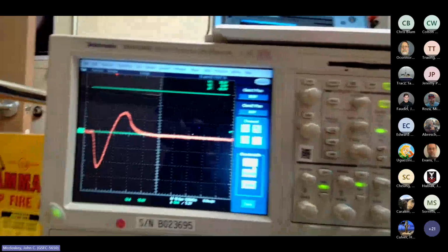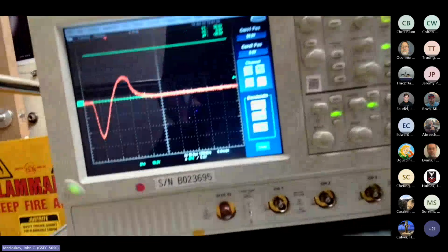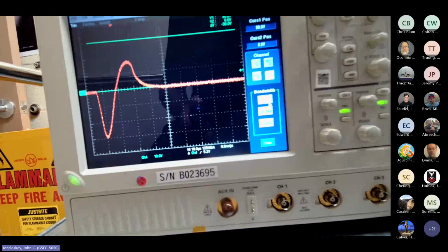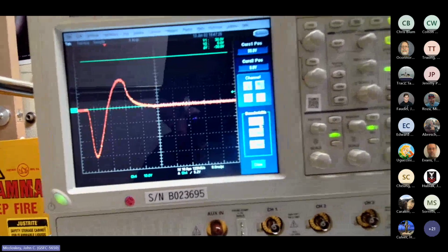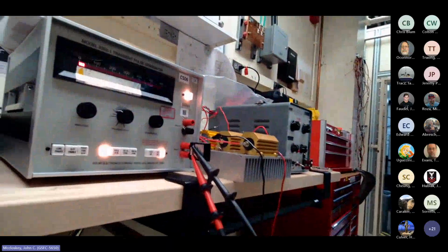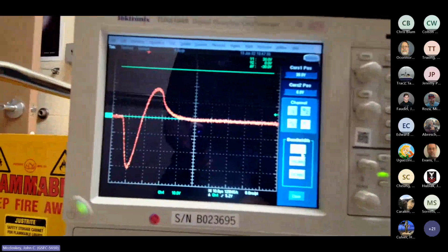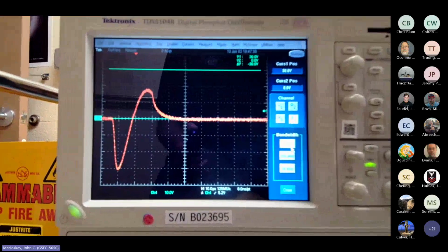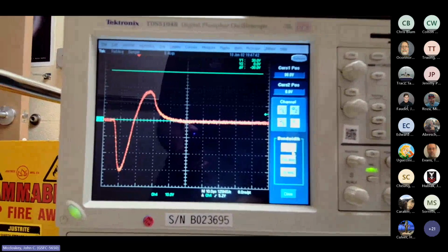But what we generally do is this. I'll increase the amplitude to 30, but we take a screenshot, we take pictures of the setup, to note how we've done the calibration. In this case, if we've done it with this resistor pack sitting right there on the generator, we take a screen capture of this and include it in the test report. So there we go. That's our pre-calibration.